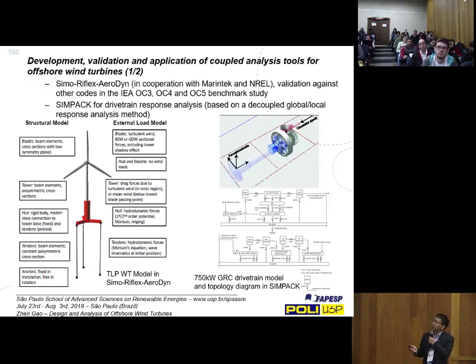Then you have typically a very detailed gearbox model, and you impose the low-speed shaft loads on the model. For a floating structure, we can also consider the motion-induced inertial loads in the gearbox. Here it is not very clearly shown, but we are able to predict the loads, the pressure between the teeth of the gears, and then you can also do structural analysis or fatigue design of the gears.